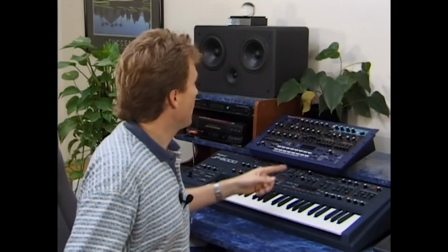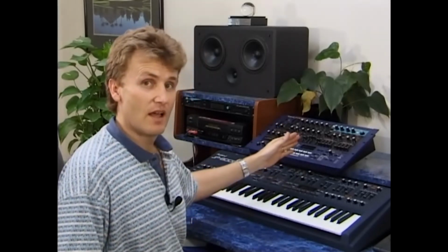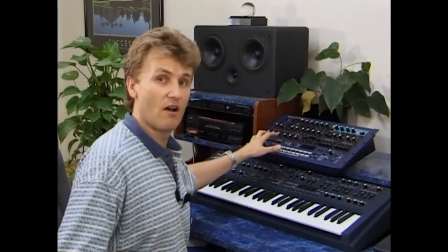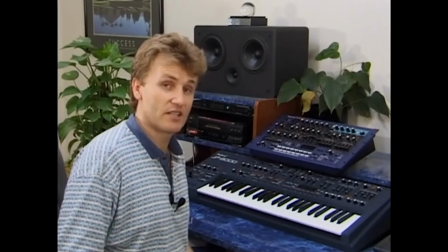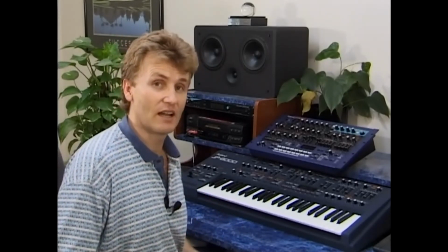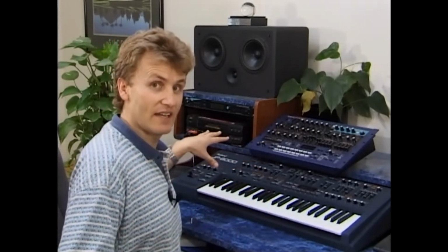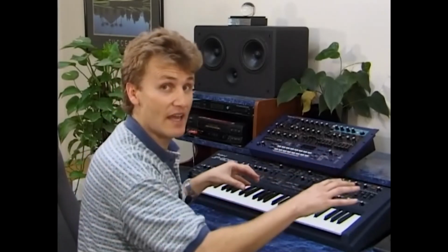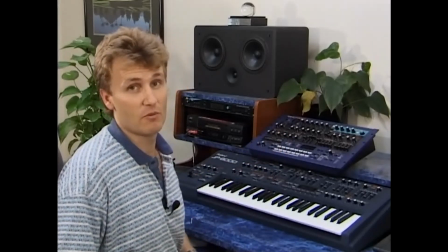Let's imagine we brought up a performance that was a split that had the lower part receiving on MIDI channel 1 and the upper part receiving on MIDI channel 2. Now if we bring up that performance, the MIDI keyboard that we have connected is going to have to provide a couple of specialized functions. First up, it's going to need to be able to send out on 2 different MIDI channels, MIDI channel 1 on the left-hand side, MIDI channel 2 on the right-hand side as well, at that precise split point that has been programmed into this performance.